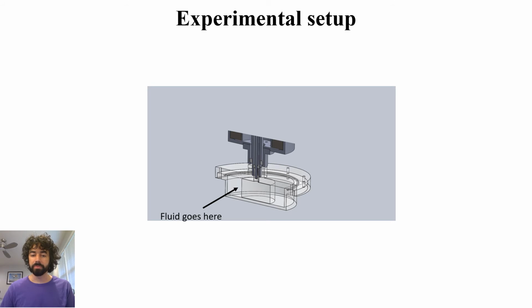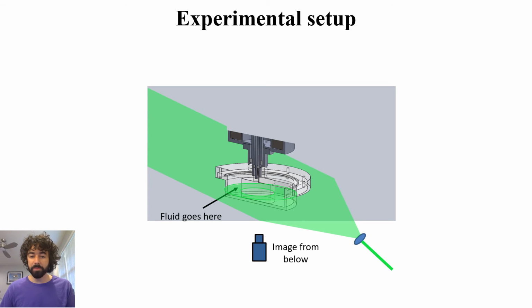Our Taylor-Couette setup is made of transparent walls, which allows for complete optical access. The cell is submerged in a temperature bath. Both the working fluid as well as the cooling fluid are index matched to the walls to remove optical distortions from the curved walls. In the experiments presented here, we shine a laser sheet at a single plane perpendicular to the axis of rotation. The height of this plane is precisely controlled. We then image from beneath and perform planar PIV.